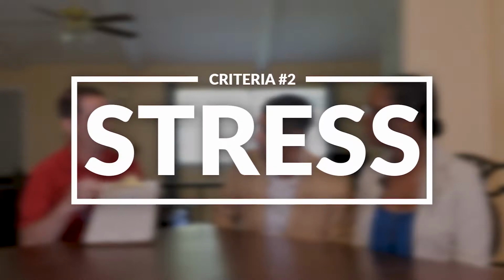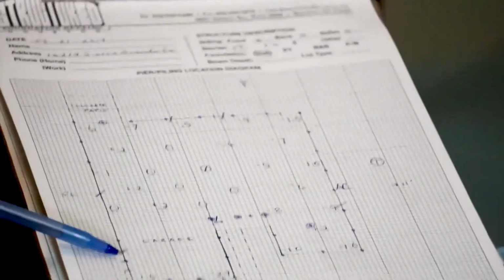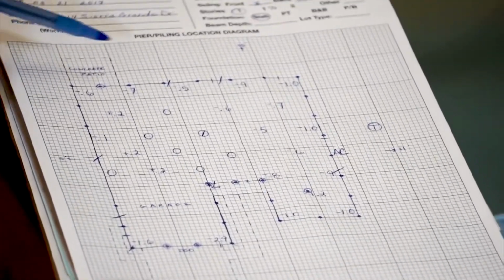I've got to have stress to accompany the drop to tell me that the house moved into that position versus being constructed into that position. So then I can simply look at my diagram and see that, okay, I've marked a crack here. I've marked some separation at the fascia board here and at the garage door frame here, and some more cracks and separation up this side, some in the back. So I do have stress signs, cracks, separations, to indicate that this deviation is due to movement. Okay, so that's number 2. So we've established we've got deviation and we've got stress to accompany it.